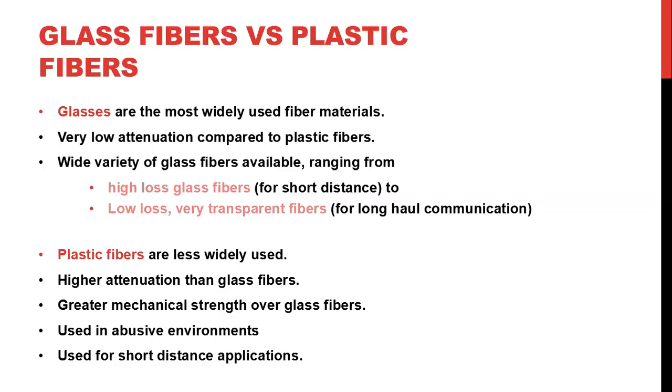We can use the glass fibers for higher temperature range, while plastic can be used only for low temperature range. As the glass is offering very less attenuation loss, we can use the glass fibers for long distance communication, while plastics are offering high attenuation loss, and therefore we can use plastic fibers only for short distance communication. And we will be using plastic fibers only in those areas where we can't use glasses.